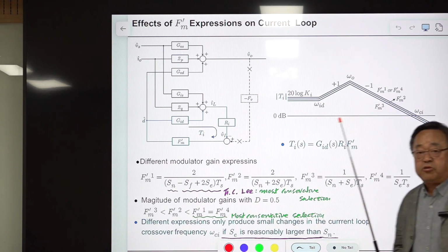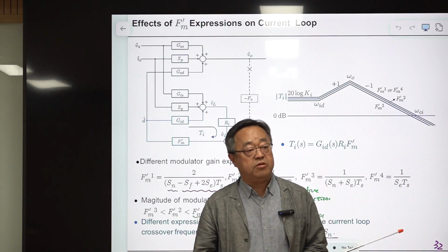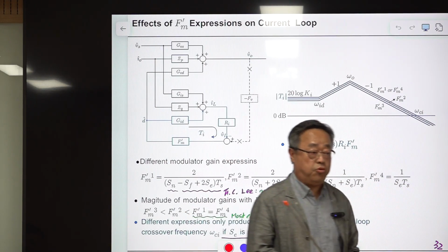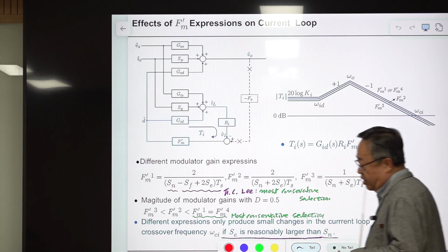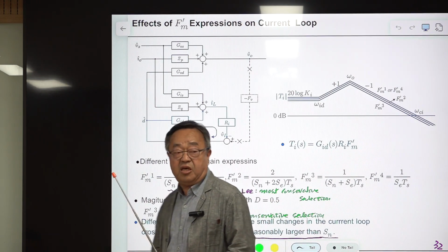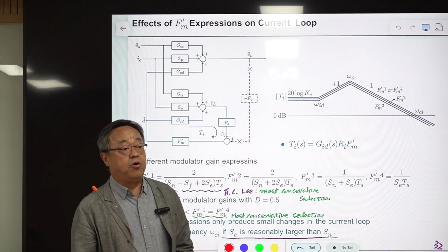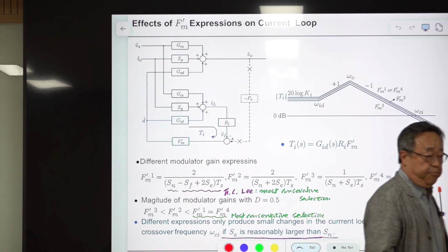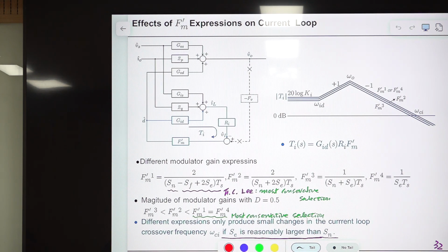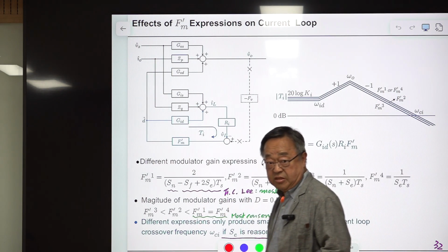In the previous lecture slide, we briefly discussed the sampling effect of the current mode control on the loop gain, the current loop characteristic of PWM converters. We found that the classical analysis keeps away from the issues of the sampling effect of current mode control by placing the loop gain 0 dB crossover frequency of the current loop at relatively low frequencies.